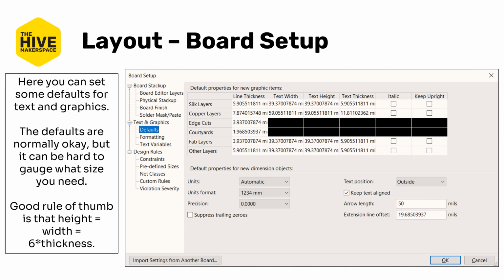It can be a really good exercise, both for you as a designer and also very useful, to make a dummy layout that only has text on it on the silkscreen layer at various height and width ratios for your reference, and then you can just print that board on a piece of paper and keep it handy for scale, because you can print it one-to-one copy.